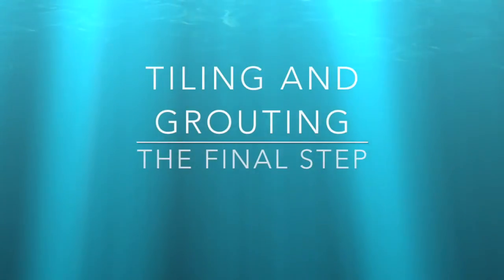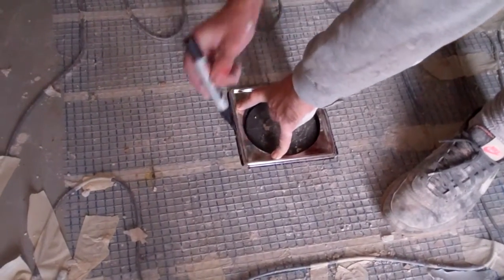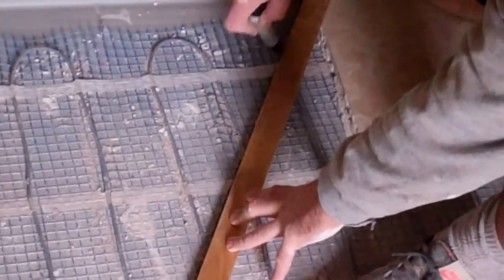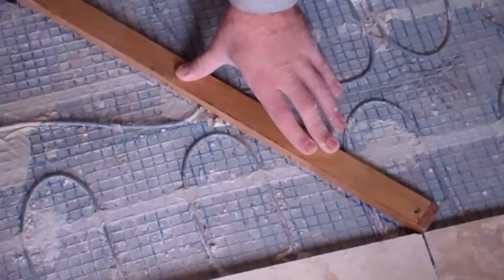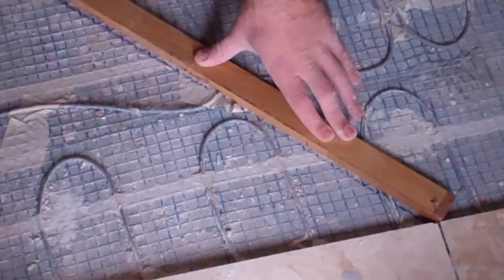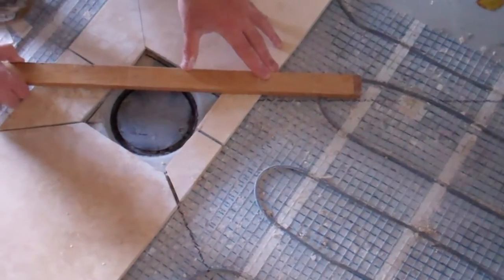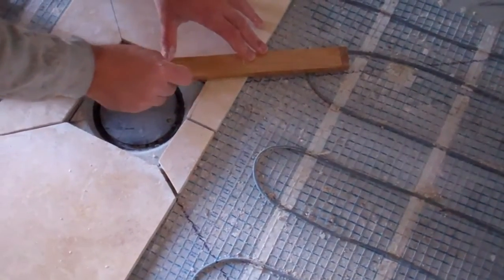Tiling and grouting, the final step. Mark up the tile cut lines in the area of the slope to falls, starting at the stainless steel tile set frame and then marking diagonally from the 4 corners of the tile set to the 4 corners of the sloped area. The tiles are then cut to intersect the diagonal lines. It is easiest to cut all the tiles prior to bedding into the tile adhesive.